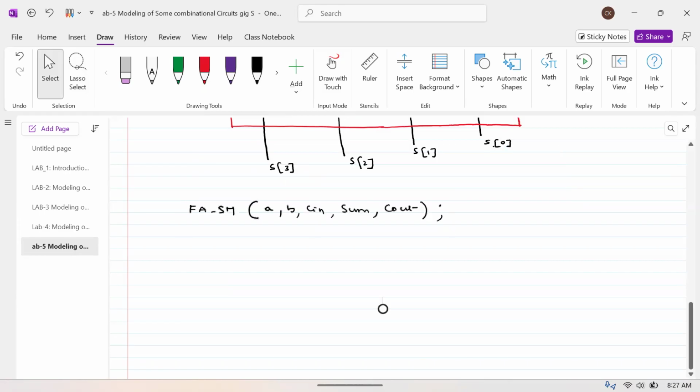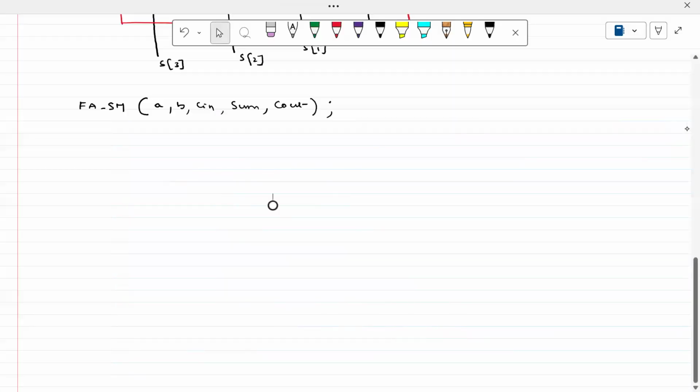Okay, let us start a Verilog program for this now. So this is the module I'm taking. This is structural modeling of full adder, implemented by using the half adder. This is already tested thoroughly, using a test bench also. It is perfectly working now. Once it is working, we have to write the 4-bit adder.